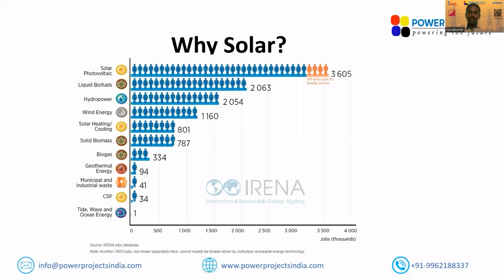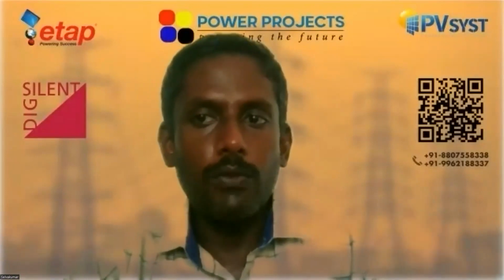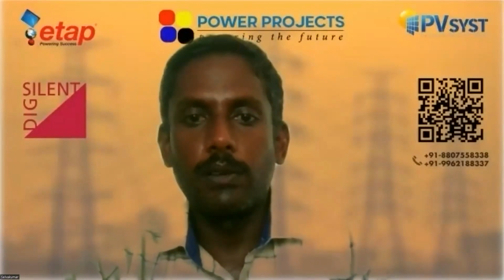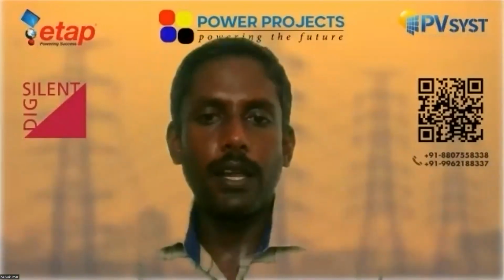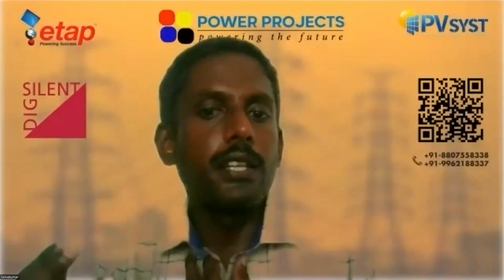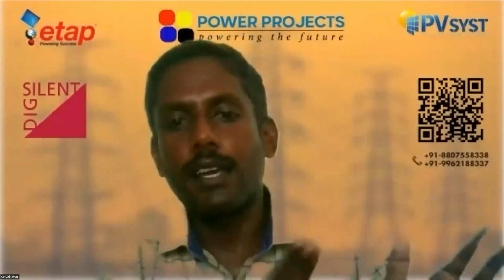When we keep adding solar, the biggest problem is the minimum short circuit current, not an increase in short circuit current. In fact, it is a reduction in the short circuit current. Why will short circuit current be less when renewables are added? Because if you compare a 100 megawatt solar plant with a 100 megawatt thermal plant, the thermal plant will have an Xd double dash impedance of, for example, 0.2 typically, right? And the transformer impedance may be 0.12 or 0.13. So approximately that will inject 3 to 4 times the rated current as short circuit current.